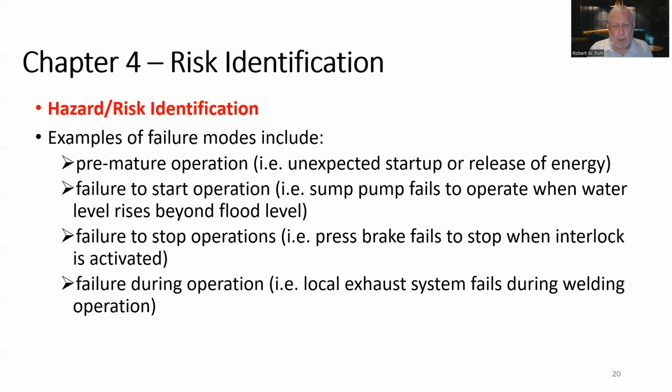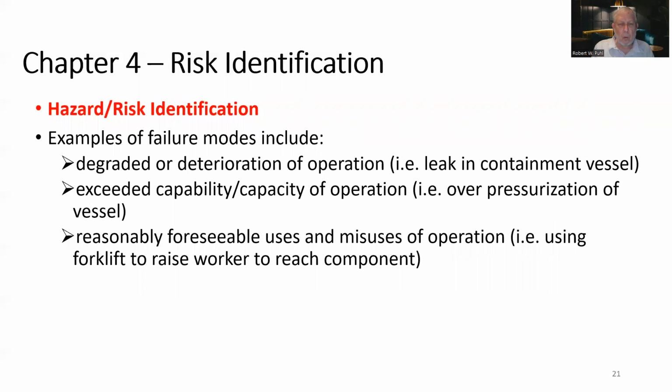Failure during operation: a local exhaust system fails during a welding operation. Degraded or deteriorated operation, such as a leak in a containment vessel. Exceeded capacity of operation: overpressurization of a vessel. Reasonably foreseeable uses and misuses of operation: using a forklift to raise a worker to reach a component.